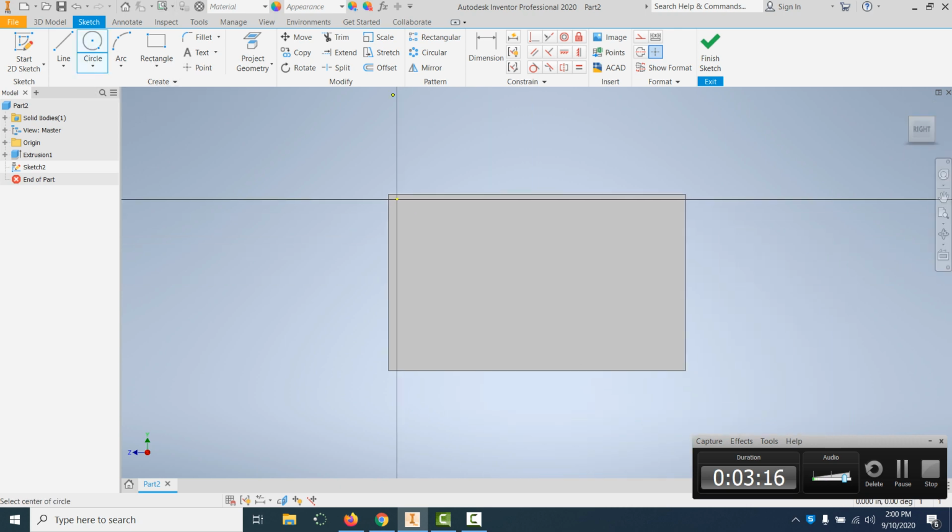I'm going to click my circle tool. I know it's in this top left quadrant, so I don't want to draw my circle all the way over here. So let's draw it close to where it's supposed to be. Click one time to start, pull it out a little, and let go of that mouse. Use the number 5 on your keyboard, and then hit enter. Okay. I need to turn my drawing tool off. This is where I'm going to use my right click of the mouse, and I'm going to hit OK.